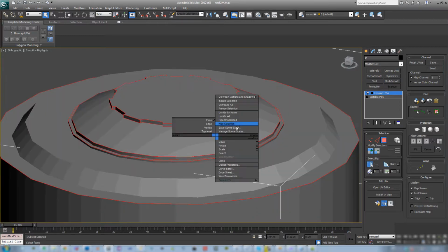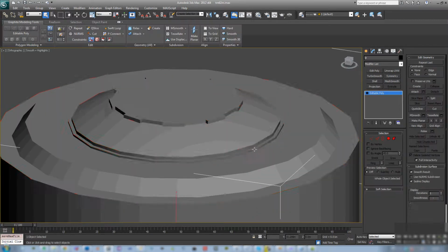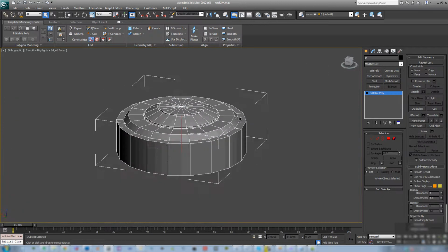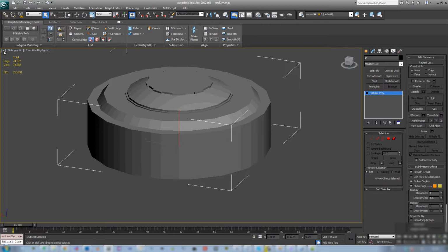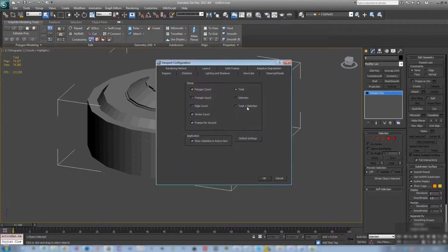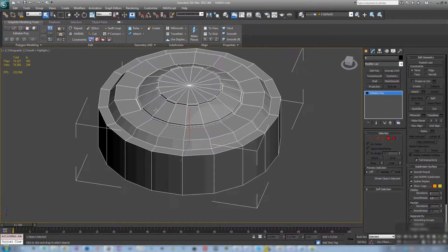Now at this point we're almost done with 3D Max. The last thing, I do my normal and occlusion bakes in XNormal usually because I don't like to work around with cages and stuff. But there's one thing that XNormal can do that I really need for the DDO workflow. That is a diffuse map bake used for materials.